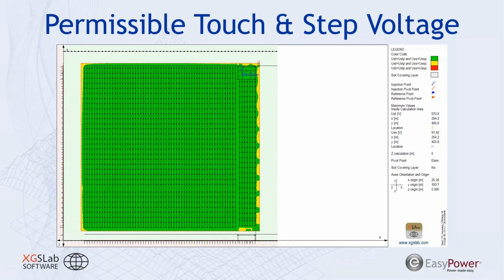One way to work around that is considering our auxiliary grounding system. Those posts are acting as several ground rods. And what they do is that they reduce the ground potential rise in that area, and they also reduce how quickly that ground potential rise drops off.